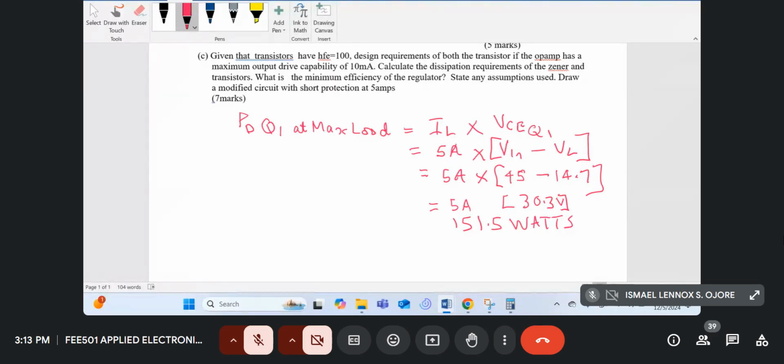So what you can do, if it was a practical problem, not an exam question, if it was like a project you're doing in the lab, then you'd have to put 2 of those transistors in parallel for it to work. You'll have to connect the outputs of those 2 2N3055 in parallel, like that. And here's where you give your driver.